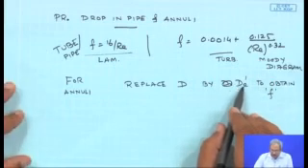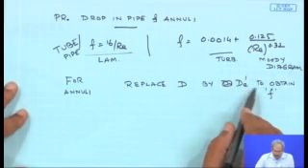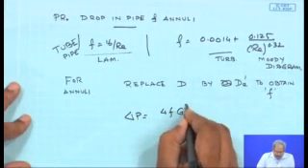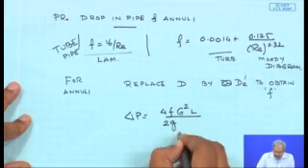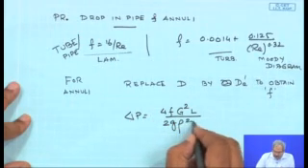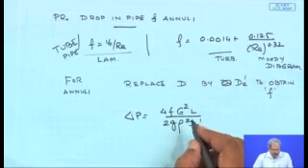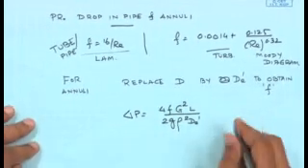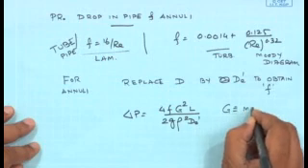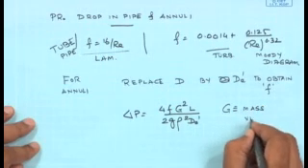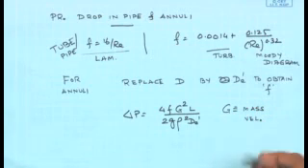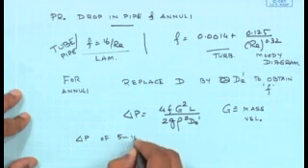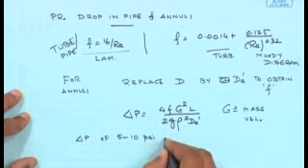So, this is the hydraulic or equivalent diameter that we have obtained, and delta P would simply be equal to 4 f G squared L by 2 g rho squared D_e prime, where G is simply the mass velocity. So, G is defined as the mass velocity. Okay. And generally a delta P of 5 to 10 psi is